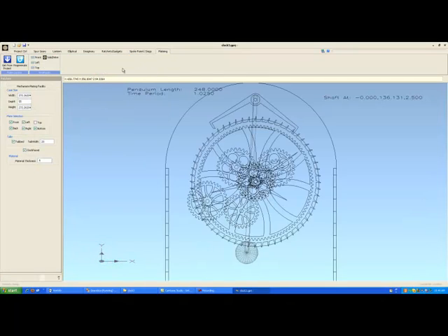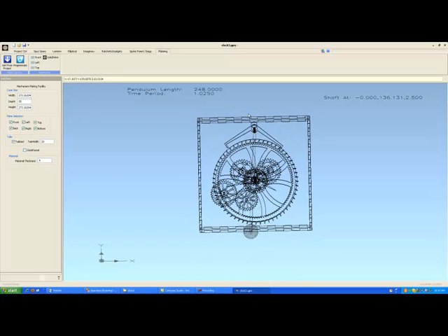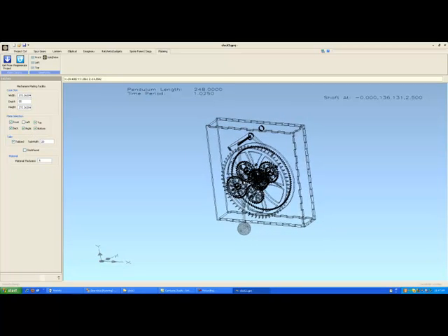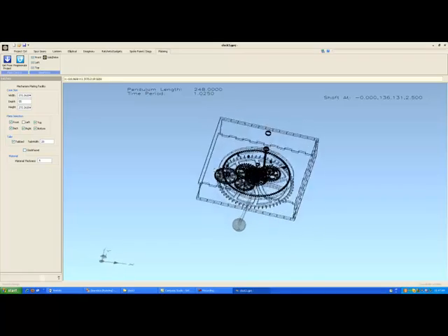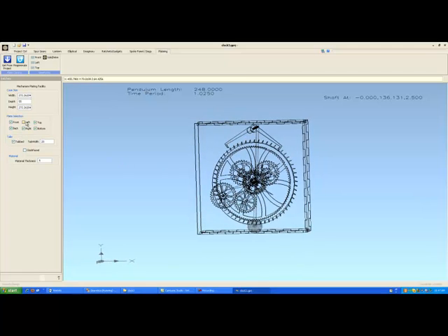On the plating, by the way, the material thickness is highly related to these tabs, and there are times when some outputs will turn on or off depending on how you've done things. For example, if I turn off clock face to give us a square box, I can then turn the top back on and the top will tab in. So you can see that now we have tabs all along. If I turn off any particular side, for example, if I turn this side off, you can see the tabs have disappeared. We'll end up with straight edges, and you won't have to put up with tabs where there is a side that you didn't intend to use.